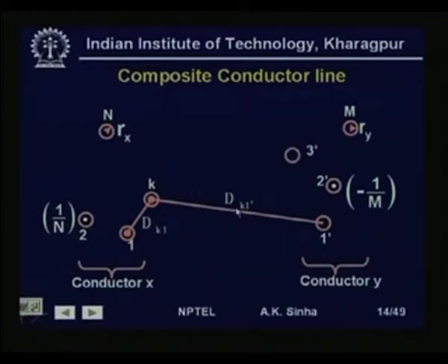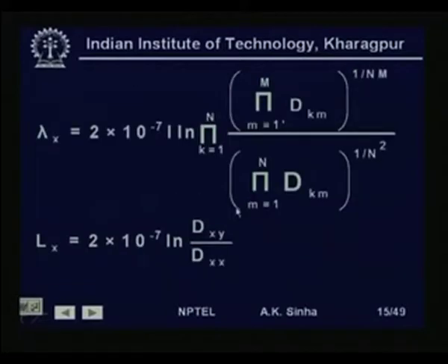So, with these we can now again find out the flux linkage of all the subconductors in conductor x.